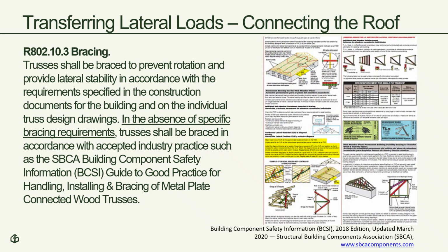Section R802.10.3 requires trusses to be braced to prevent rotation and for lateral stability, per the truss design. In absence of specific bracing requirements, the Building Component Safety Information Guide, published by the Structural Building Components Association, applies.